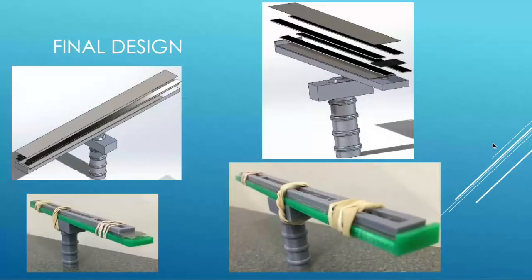This was the final design that was chosen. The 7th iteration of the CO2 chamber was what we went with. You can see in the top right image the CO2 adapter that plugs right into the CO2 chamber. And we have the steel-backed porous membrane that'll allow the CO2 to go through. And we have those red silicone tapes that will house the microchannel and hold everything together.